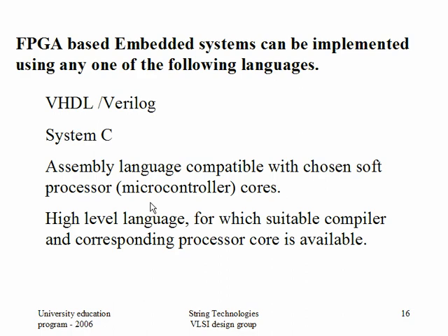See, what I'm trying to say is, you are writing some portion of the VHDL code. Acha, for people who did not attend the VHDL session, I want to give one important concept. How are VHDL code and Verilog code different from conventional C code? At least my VLSI team people should give the answer. The main thing is, VHDL and Verilog code are concurrent in nature. By default, when I write VHDL code, 10 lines are running in parallel. What do you mean by that? When I implement it in an FPGA, all 10 lines will be implemented in parallel on different pieces of hardware.